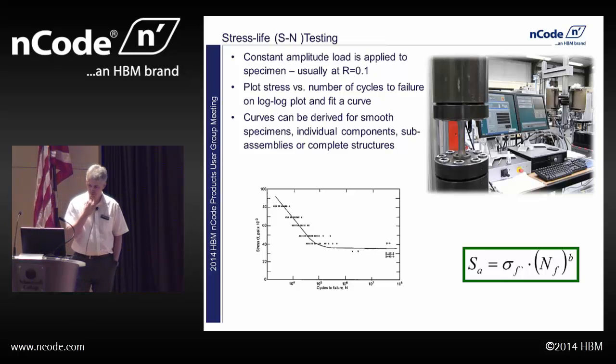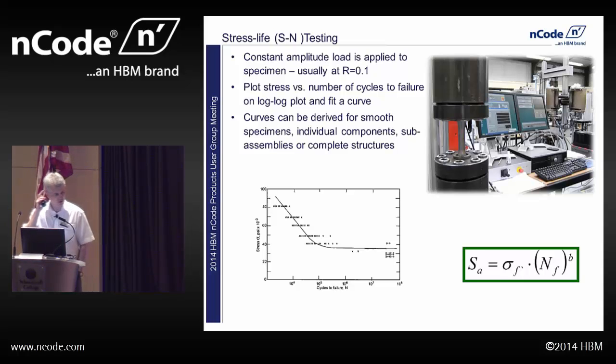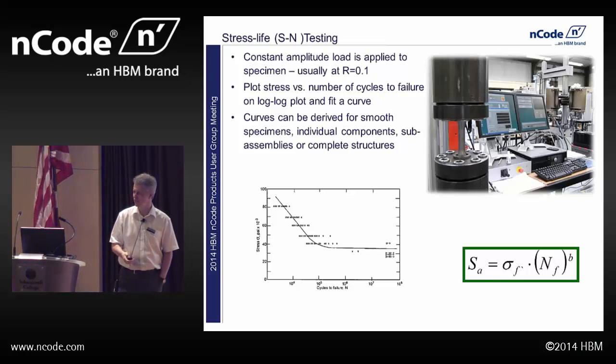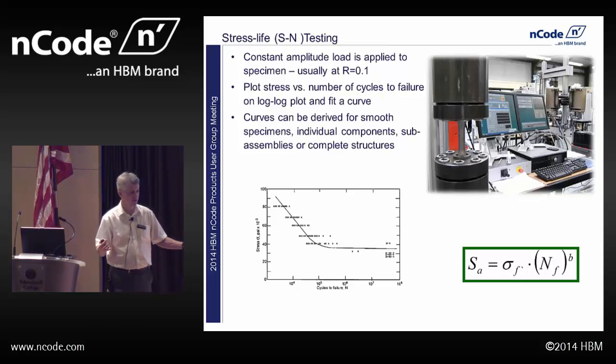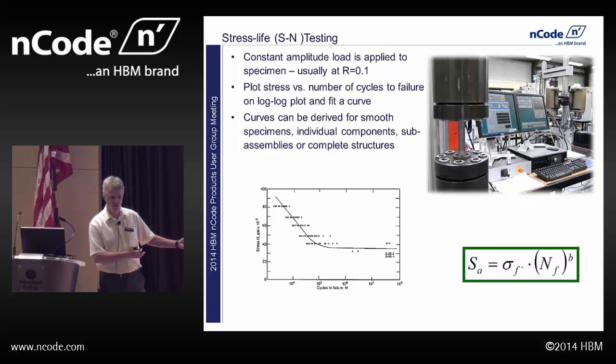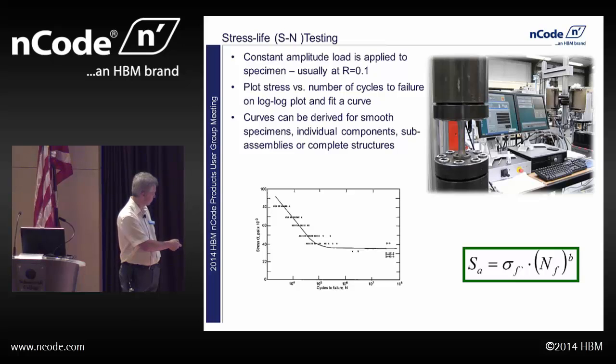And then what sort of testing do you have to do in order to determine the fatigue performance? So two major types. I guess the first was in the 19th century, Wöhler, 1850 something. So originally Wöhler did this sort of test with axles that were failing. You wanted to simulate what happened on the trains. So he brought the axle in, hung a weight on it, rotated it. You run it at a constant stress level, and you get failures due to that. And that's pretty much what that stress life curve is plotting, where you've got stress level against cycles to failure.